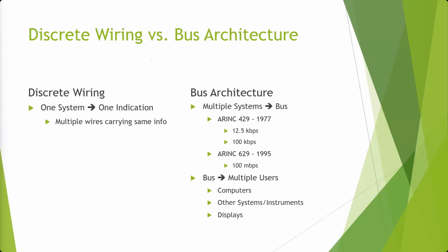You could have 2 wires coming off sometimes, right? Maybe you need to have pitot and static going to gauge 3, right? And gauge 1 maybe is just static for altitude, right? Altimeter, airspeed, something like that. So it's not just wiring, if you're doing electronic, it can also be piping as well. Those outputs could be sensors that go to a light or something like that too.